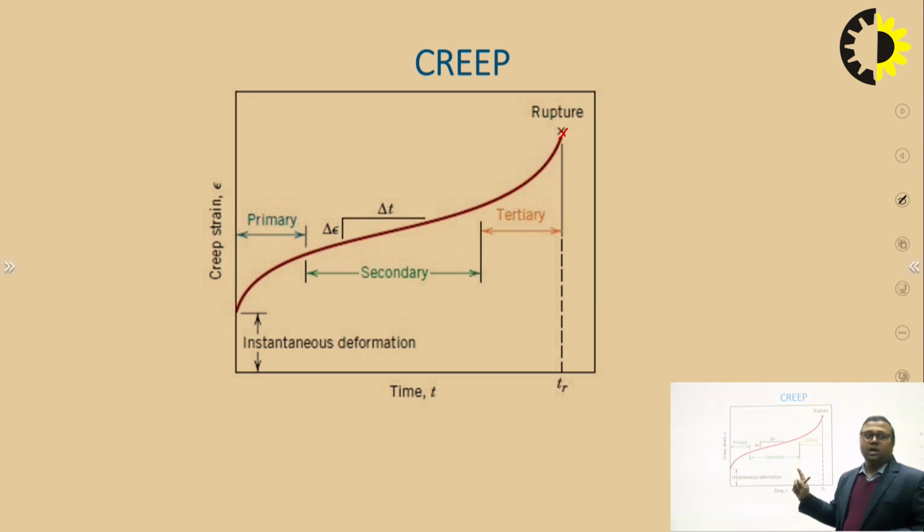This graph has been drawn for a particular temperature and a particular stress. By applying a particular load onto a material and keeping that material for a longer duration of time, we see the deformation, which is known as the creep strain.